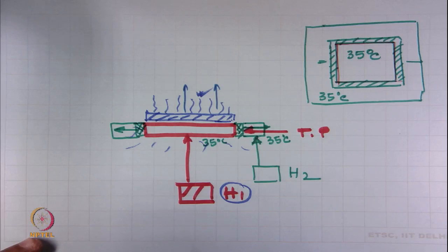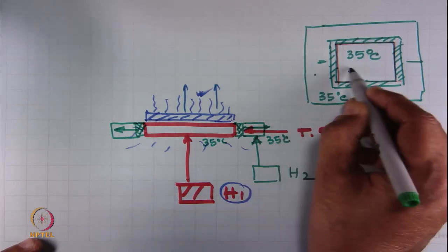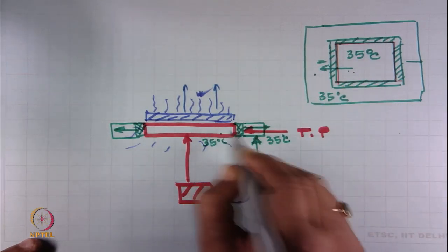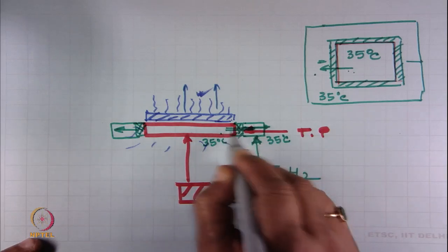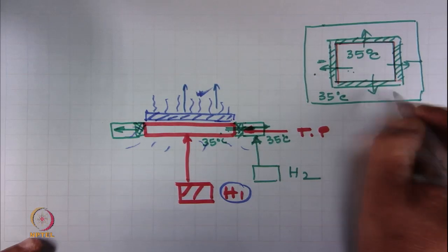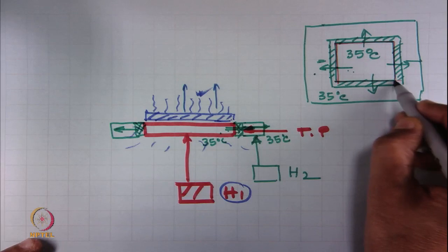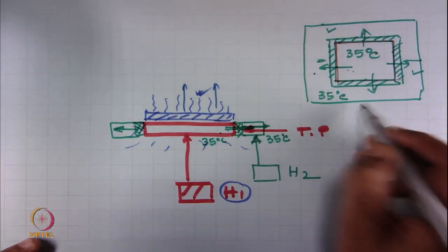That means, there is no temperature gradient. So, heat will not try to flow from the test plate to the guard ring. So, the sideway flow of heat is being blocked using two techniques, one is the insulating cork, another is maintaining the same temperature of the guard ring.